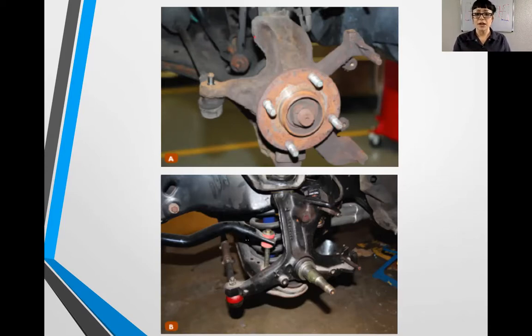That is for steering. So this rod is going to push and pull the knuckle to change the direction of the vehicle. Nifty, right? Up at the top of our knuckle and the bottom of our knuckle, again, we need to allow for that pivot action. So this is where it connects to our control arms, usually through a ball joint.